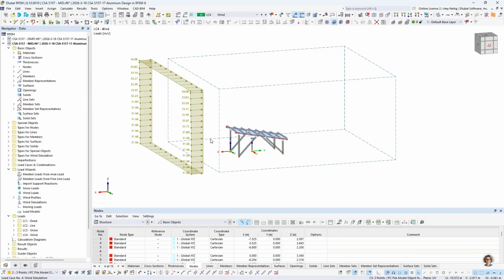And in our case today, we have a freestanding carport. So therefore, the code isn't so clear on exactly what loads we are supposed to apply to our structure. So this might well be a situation where we use something like CFD wind analysis just to verify our assumptions, our guesses, in addition to referring to the NBC standard for these wind loads.